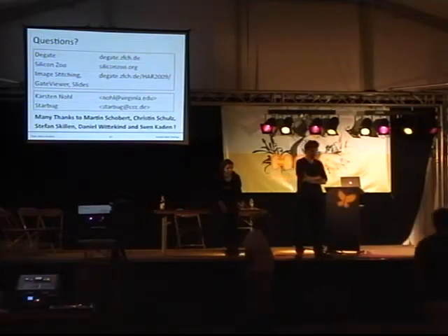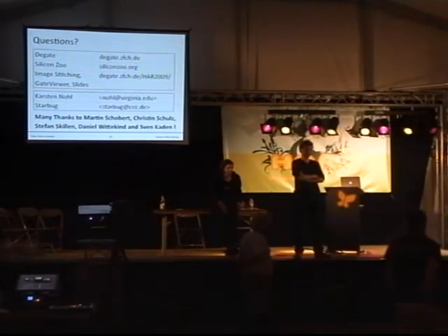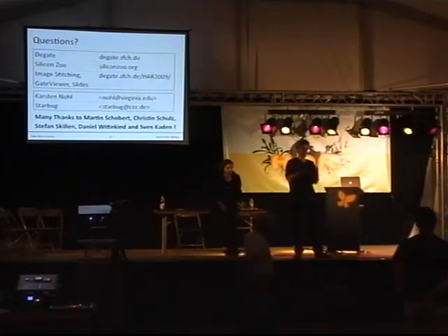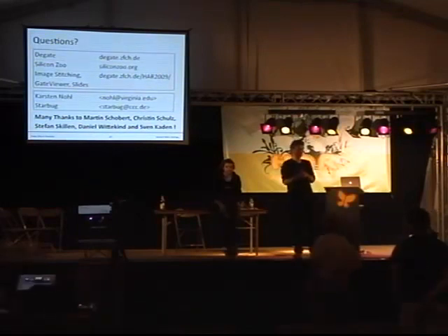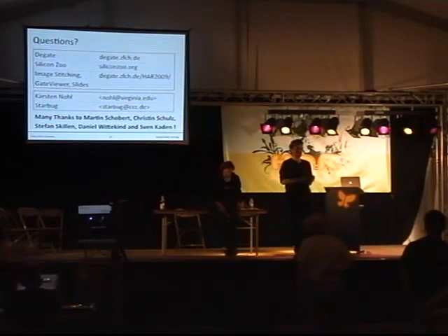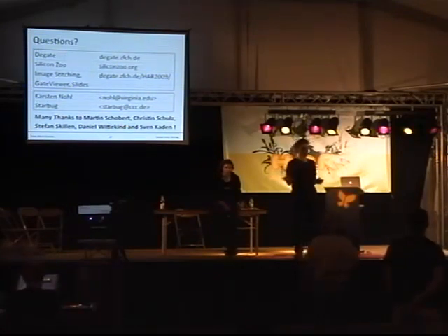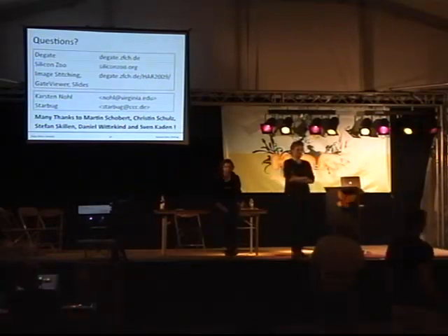Most often what happens is the person designing the chip doesn't even know what the gate looks like. So in his tool chain, there is no such thing as a fully specified gate. It will draw a block saying, put a 2 NAND here. It will send it off to the foundry in the standard format, and only in the foundry, these black boxes will be filled, right? We can, of course, see when it's using the same library, the same foundry, right? Those will use the same patterns.